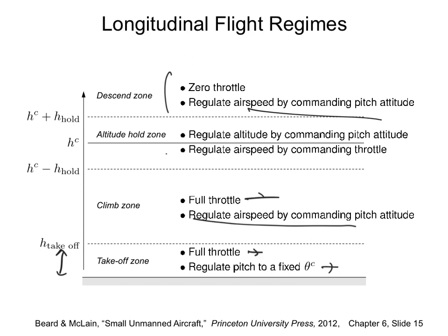Before we move on, longitudinal control autopilot. We have already covered the lateral autopilot. Now we are moving to the longitudinal autopilot, which is a little bit more involved than the lateral. The lateral only had your phi, chi and beta, and was kind of simple. But here the main thing is the altitude. This chart basically shows you the three different zones. So there is a takeoff zone.